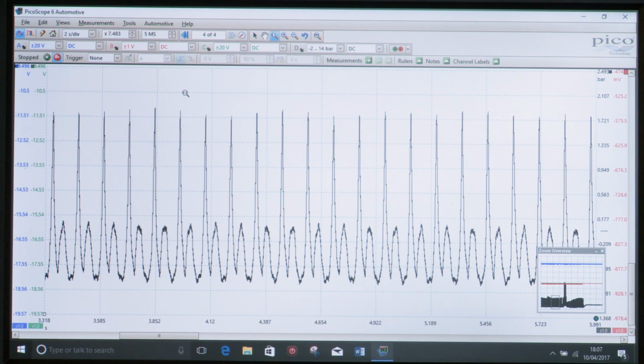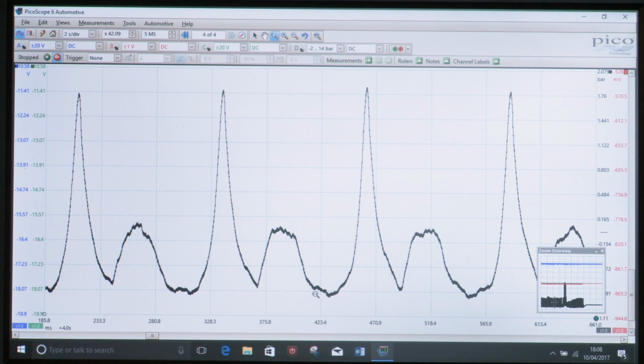So, how can we then analyse the results? Well, first of all, we only need to look at a couple of events. So let's pick, if you like, 2 or 3 compression events. We're just looking at one cylinder event now. Now we need to overlay on top of this the theoretical position of the engine. So let's ask for 4 cursors. So we're now going to convert pressure into an angular relationship.